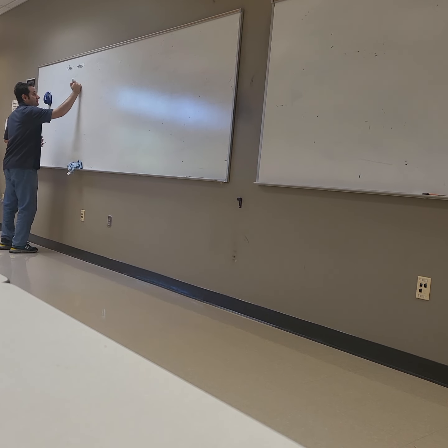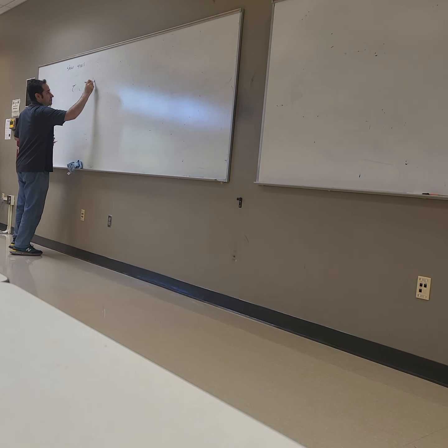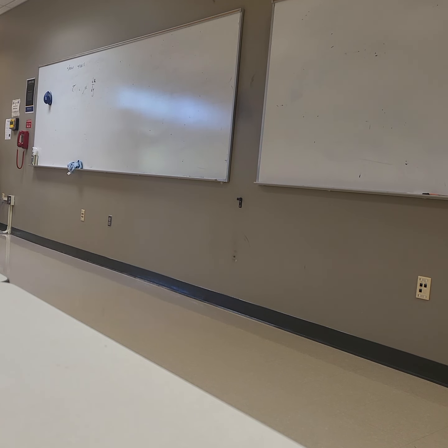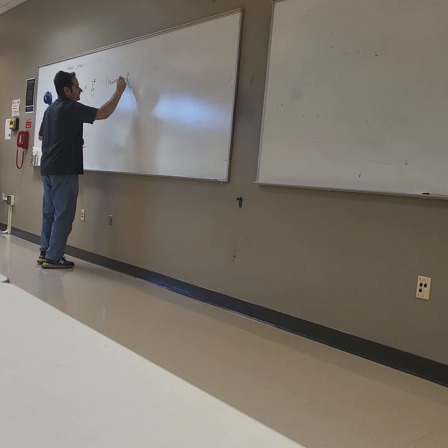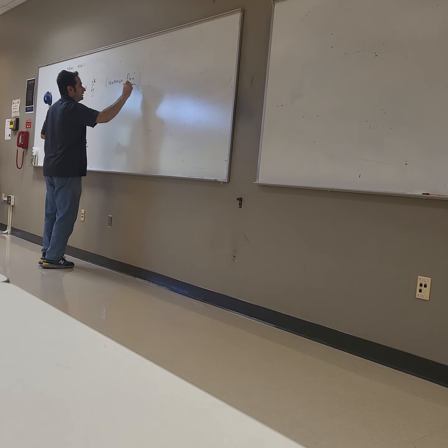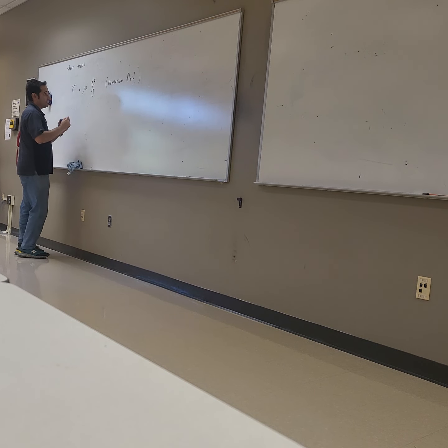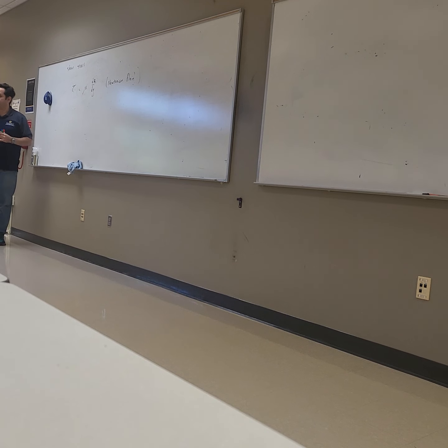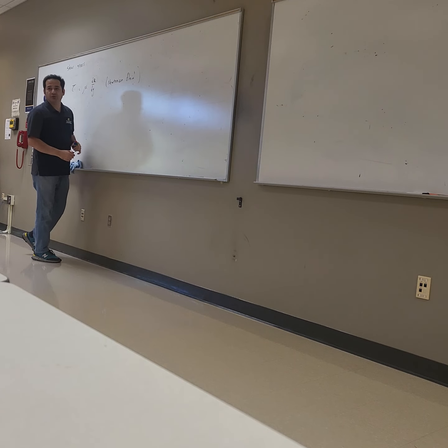If the relation between shear stress and velocity is linear, tau equals mu du/dy, where u is velocity and y is the direction orthogonal to the direction of flow, right? In that case, we would say this is a Newtonian fluid. Obviously, you have a relation with the velocity gradient, not velocity itself. Any relation that is not similar to that is called a non-Newtonian fluid.